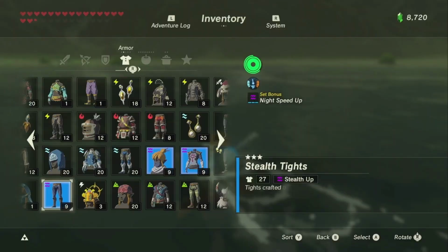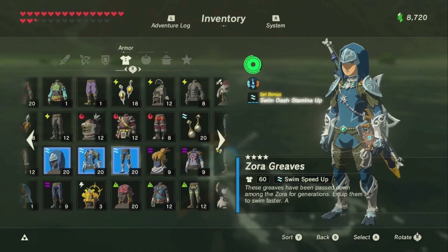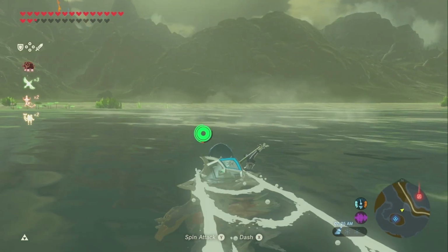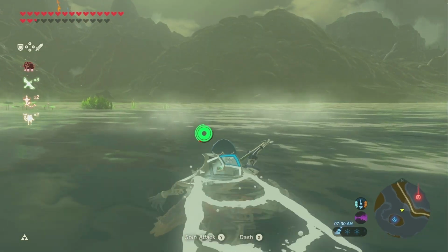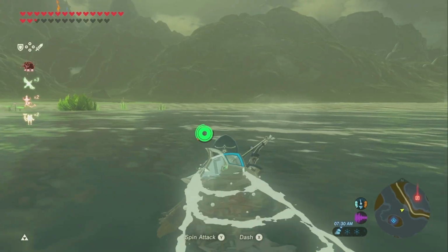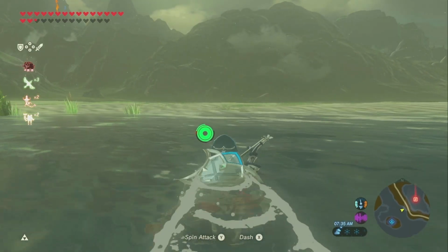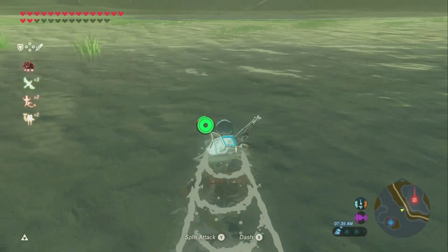Poor water pressure and flow on larger homes. Some large homes have water service pipes of 1 inch to 1.5 inch in diameter. The pressure and flow in these houses can be affected by residential water heaters, which typically have 3/4 inch connections.